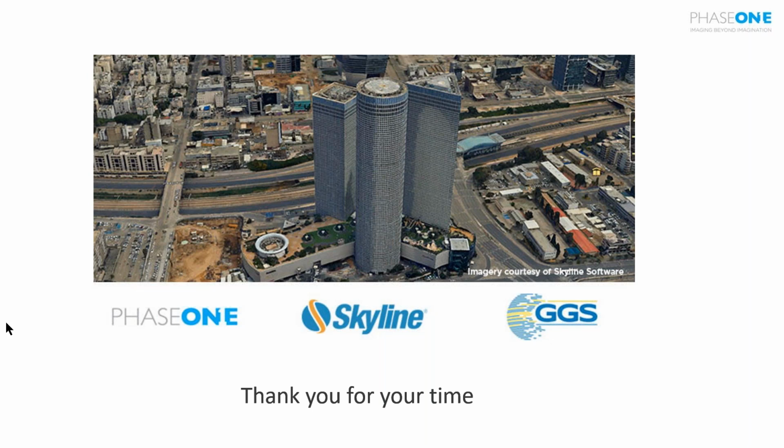There's a question, can we also see DEM and DTM in Terra Explorer? The answer is yes. You could load in elevation data and regular raster imagery, ortho imagery, and display them in what we call 2.5D. 3D is a full 3D mesh model and can have a view underneath things. 2.5D is a gridded DTM or DEM with the imagery on top.